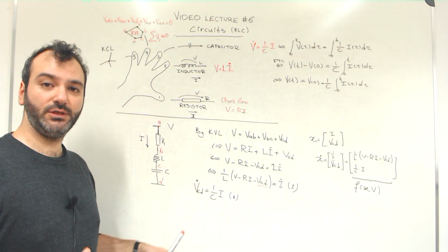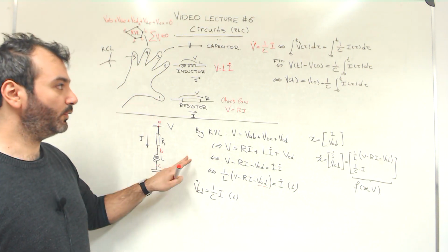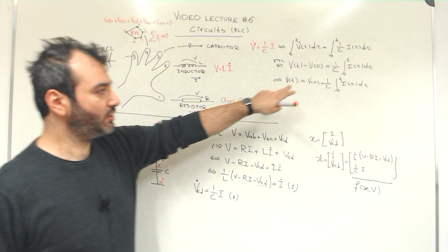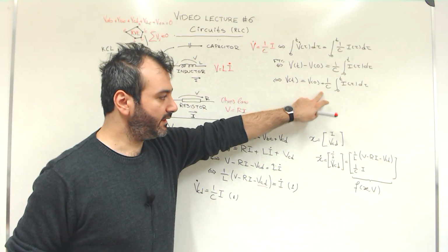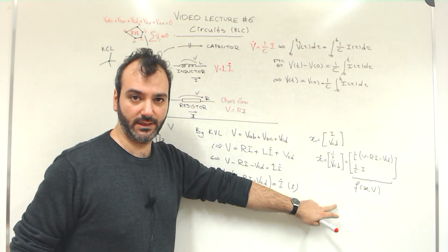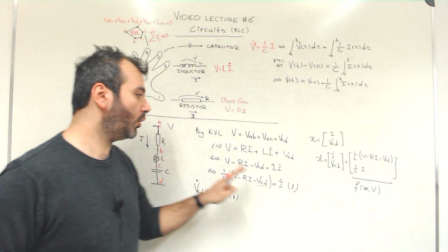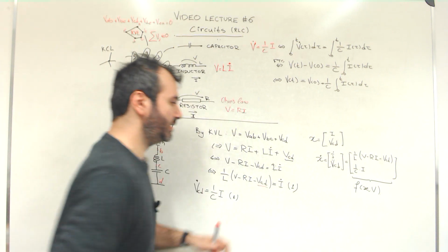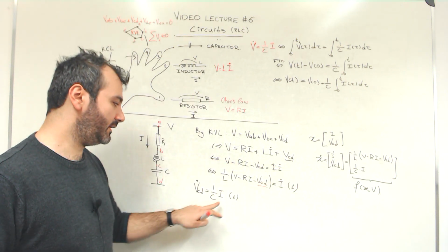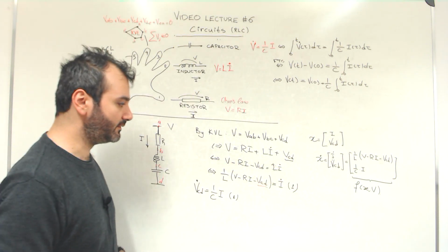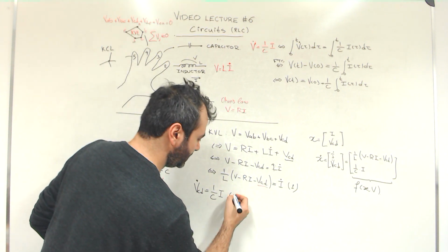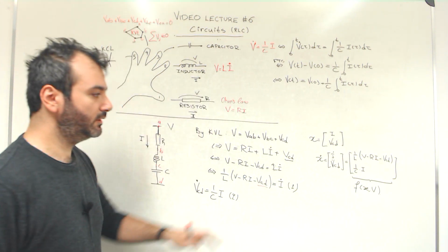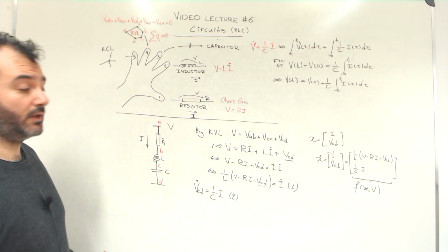Now the two approaches are absolutely equivalent. We can either use this equation and then derive an integral differential equation as we did before, or we can do this little trick, not touch VCD yet, and then write down the differential equation that governs it. This is equation number 1, this is equation number 2, and then this is the state space representation.